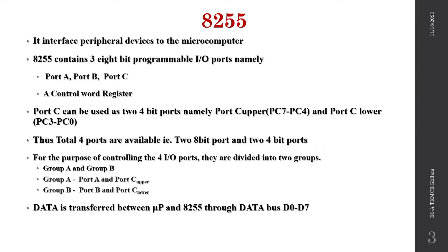It contains three 8-bit programmable I/O ports, namely port A, port B and port C, and a control word register. Port C can be used as two 4-bit ports, namely port C upper and port C lower.